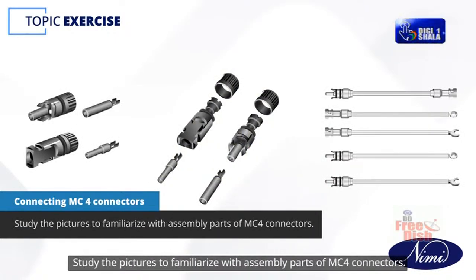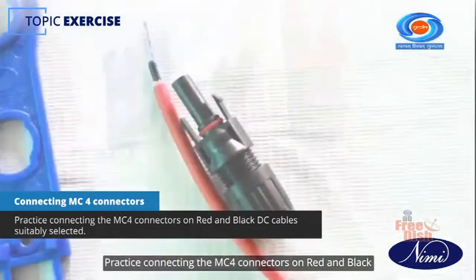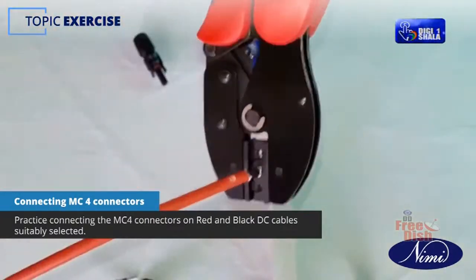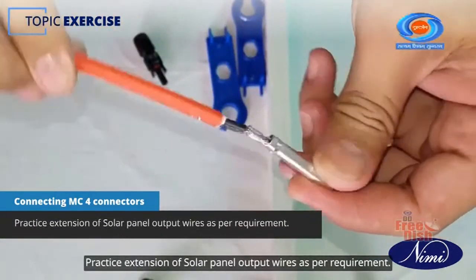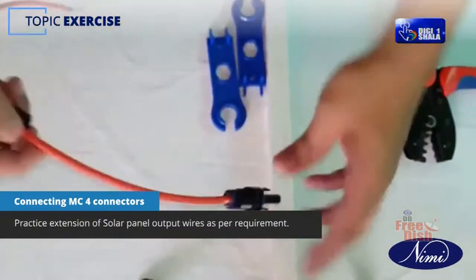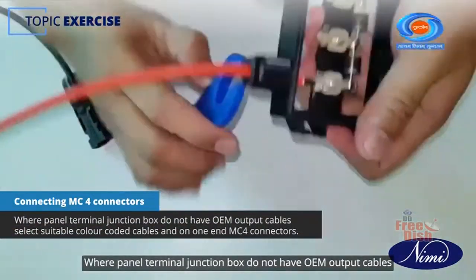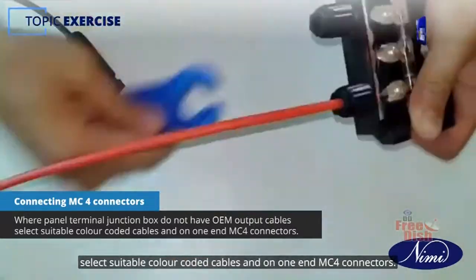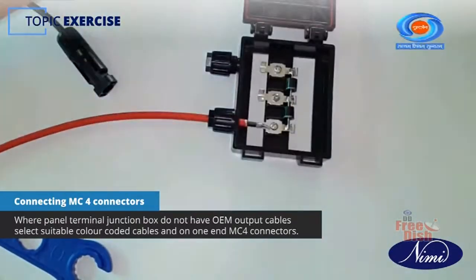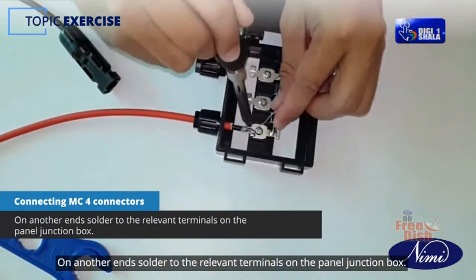Study the pictures to familiarize with assembly parts of MC4 connectors. Practice connecting the MC4 connectors on red and black DC cables suitably selected. Practice extension of solar panel output wires as per requirement. Where panel terminal junction box do not have OEM output cables, select suitable color coded cables and on one end fit MC4 connectors. On another end, solder to the relevant terminals on the panel junction box.